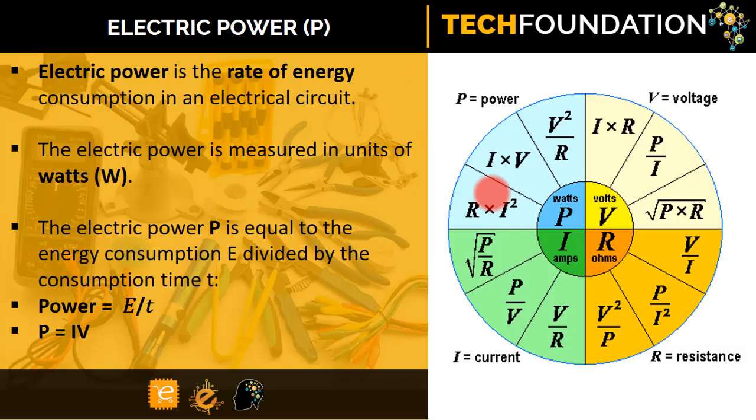Okay, so let's also look at electric power. Power is defined as the rate of doing work. Therefore, in electric circuit, we can define power as the rate of energy consumption, because work done is a form of energy. Okay, work is measured in joules, energy is measured in joules. Now power is measured in watt, that is joule per second. Now, please note, usually you hear people talking about batteries storing power. Please, batteries do not store power. Batteries store energy. Batteries store electric energy.